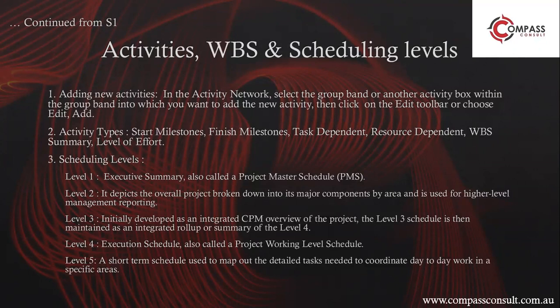Level 4 is basically a standard schedule which most of the contractor companies make, like for a 5-year, 7-year project. This is a very standard schedule level that is being developed during the initiation of the project, during the planning phase. Level 5 is basically a short-term schedule used to map out the detailed tasks. So there are 3-month rolling programs, there are 4-week rolling programs.